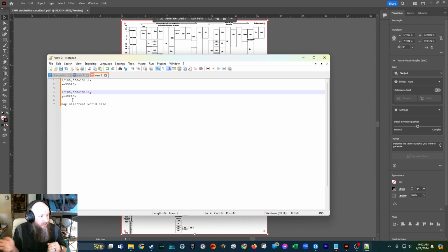At half-inch wide boxes. So we've proportionally set this up to be a page size at 1 to 100,000. And a lot of people ask, why do we do that? It's a simple process to make sure that all of our maps are exported at scale. So we don't want to set it to 1 to 1, we want to make sure that everything is proportional, and it's a quick, easy thing to set all of our data frames to be at the scale of the map, and then we have less that we need to pay attention to, like, does this data frame need to be at 1 to 1?